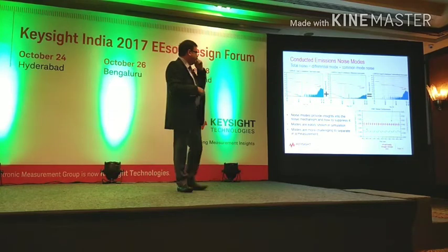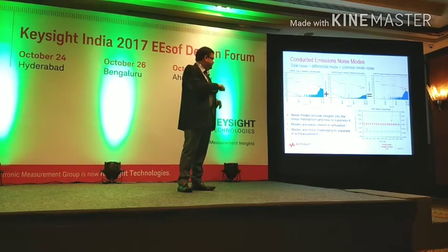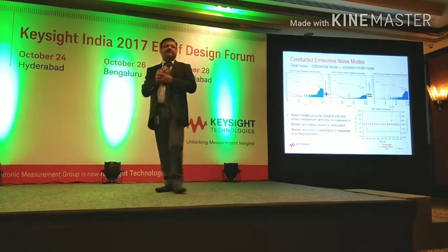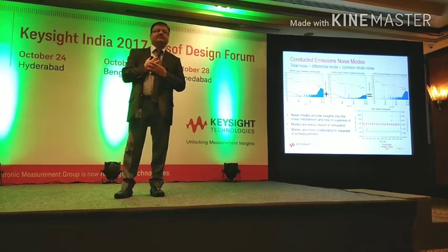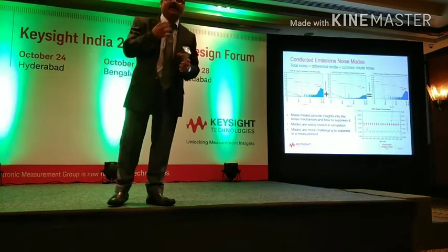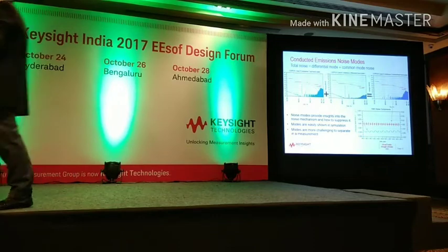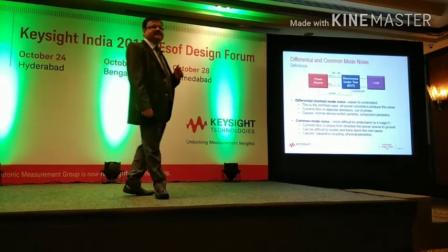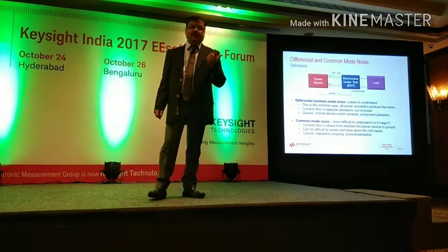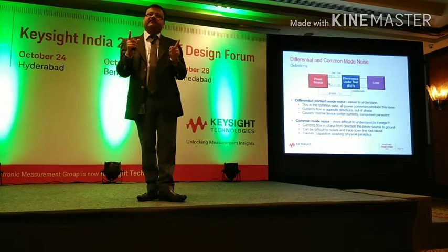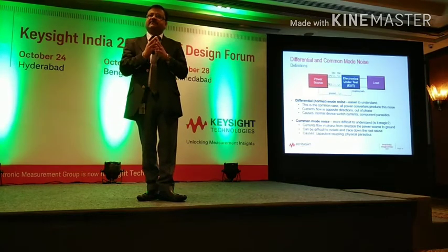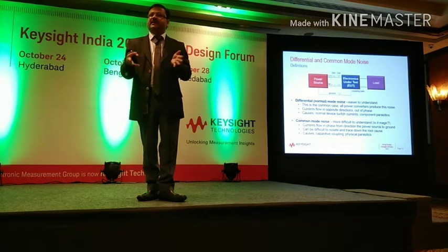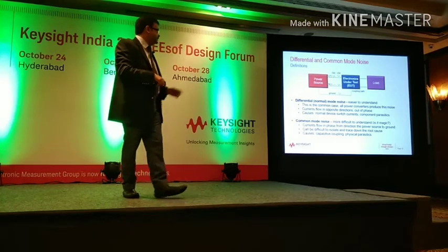Okay, so before we go in, when we say noise mode, how many types of noise can you have in your system? Everybody give answers. Probably you saw that in the slide. You guys have a good idea. So two noise modes can exist: differential mode noise and common mode noise. Now, both of them will have different characteristics. Both of them will have different suppression techniques depending on what's applicable for your system.